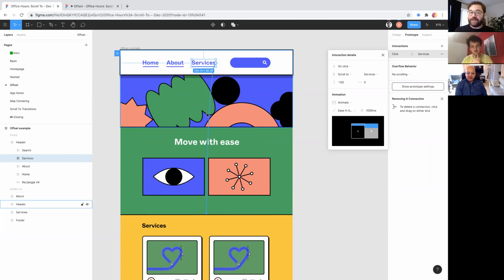So if your offset is not working, and you've got to present something in about 10 minutes or so, and you just can't get the heights right, definitely try messing with the offset a little bit and see if that helps you get exactly what you're looking for. Then you can go back and figure out if there was a better object that you should have connected it to, or if you just want to continue using offsets like that. Keep in mind that the offset itself will always stay the same height as well. So if you happen to move your object or your layer, you're still going to have that same offset unless you update the offset as well.